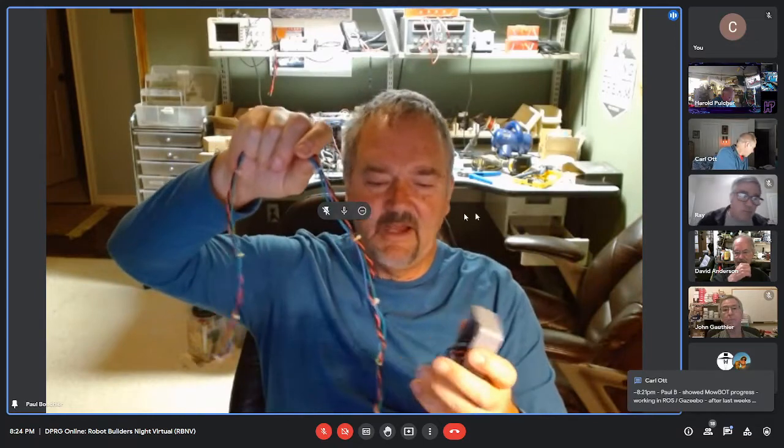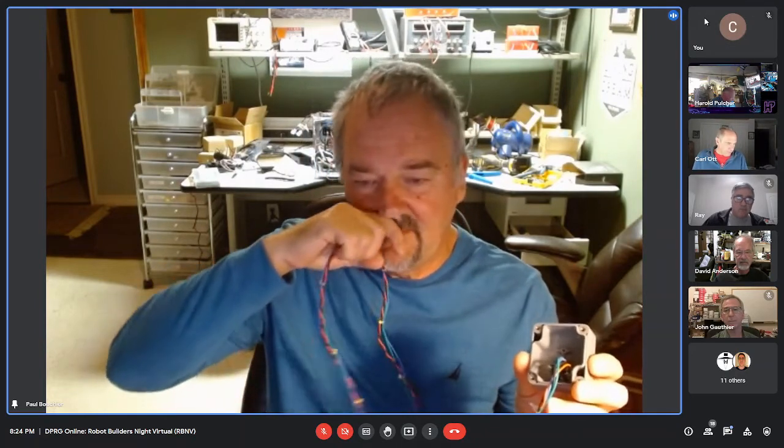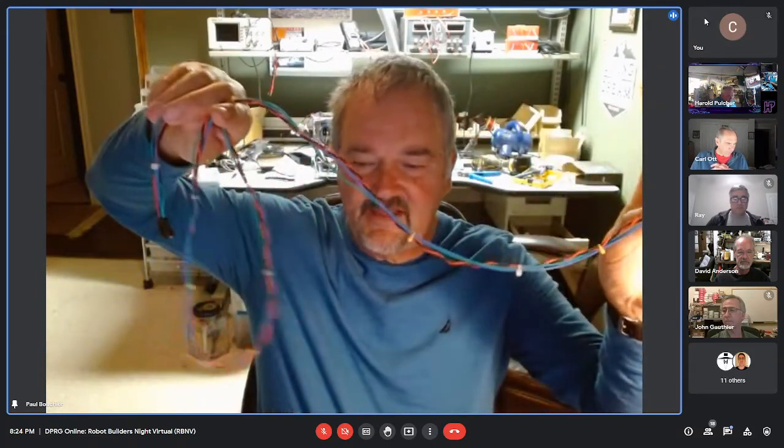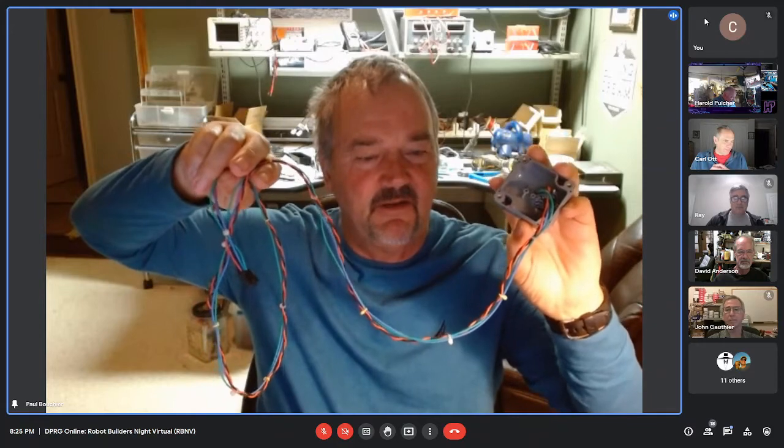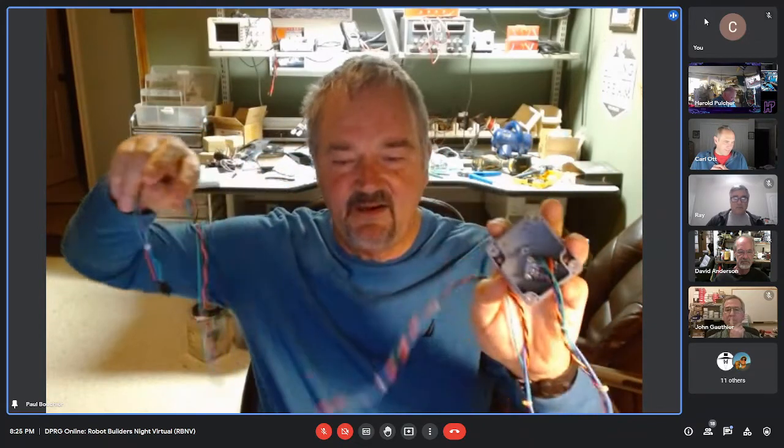Maybe if you pin me to your screen, you can see this full screen. I got a BNO055, which is a gyro that I'll use for direction, and I have a couple of questions for any of you who've messed with this BNO055. First, is this too long of a cable? It's I2C, and apparently it and the ESP32 run 400 kilobit fast I2C. I don't know if this is too long of a cable. Does anyone have any experience with cable lengths like this? It's about a meter.